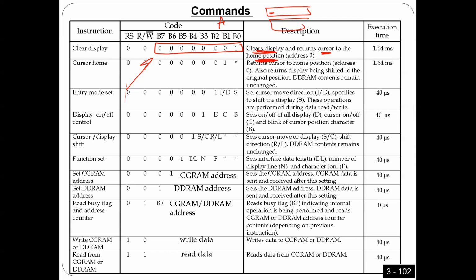One more thing I want to tell you guys, a very important thing. Listen to me. Here, I'm explaining our LCD. If you do your own project and you use a different LCD, programming it will be similar to what I explained here. However, you have to get the data sheet of the LCD you are using, and in this data sheet they should write what command is what.